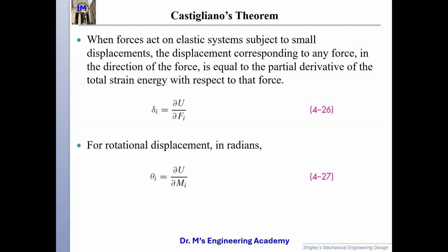Some students might be asking, and this is kind of confusing: if I apply a load, I can get this delta i. What if I don't have an actual load? Can I still use this equation to get the corresponding either deflection or angle? The answer is yes.